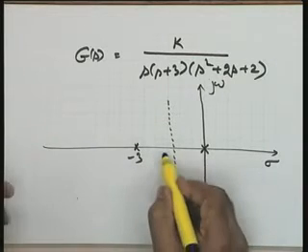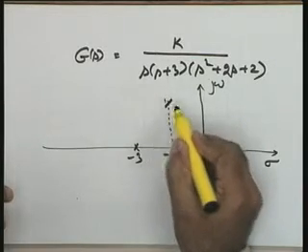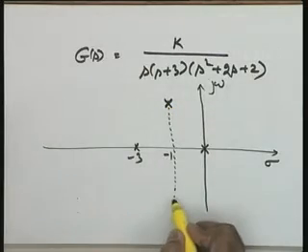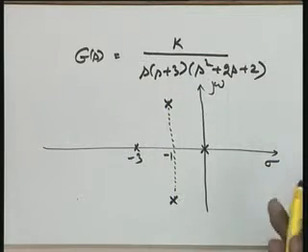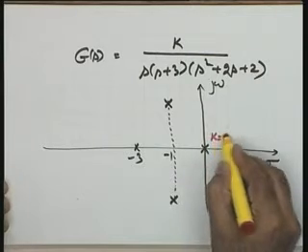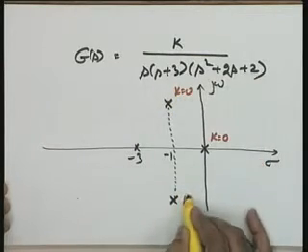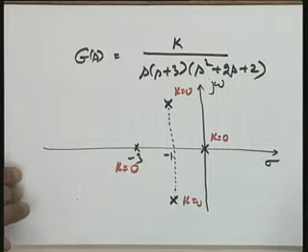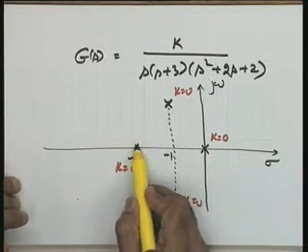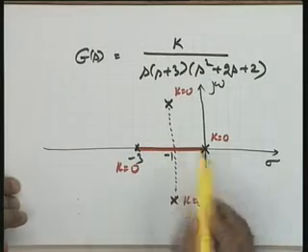Minus 1 plus minus j. So, let us take minus 1 over here. Okay, I am sorry, this is not to scale, but it does not matter. This is the situation as far as complex poles are concerned, though the pole-zero configuration which I have given you is not to scale. Now, you just see in this particular case, 1, 2, 3, 4, there are 4 poles, and therefore, there will be 4 root locus branches, k is equal to 0. These are the starting points. Okay. So, in this case I know that this particular portion will be on the root locus.